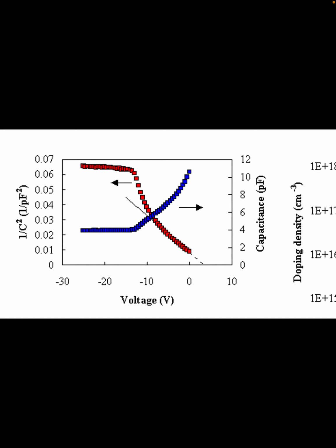You can see the capacitance is shown here. As your reverse bias potential is increased, your capacitance actually decreases, which is understandable. Your width increases, so it is epsilon by width, so your capacitance value should decrease. After a particular level, the capacitance value does not change a whole lot because you have almost depleted the entire region,